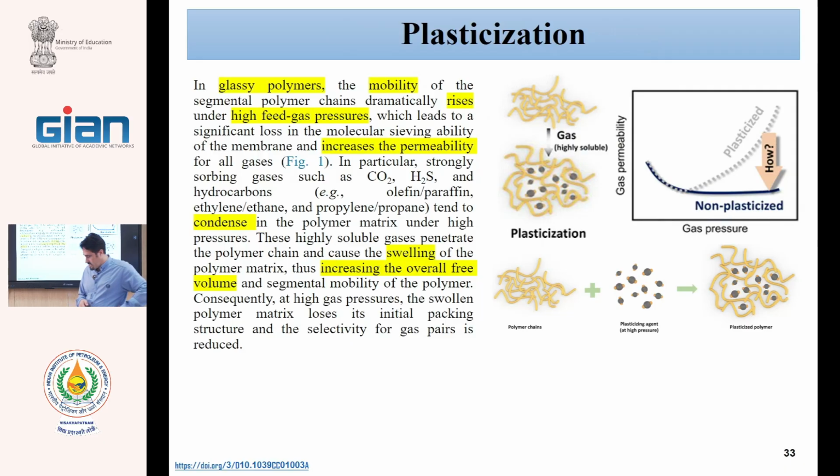In the liquid membrane filtration, MF, UF and others, we have fouling. That fouling causes a reduction of the performance. In gas separation, we also have fouling, but usually we do not say fouling. In this case, say aging or plasticization. Similar to fouling, the selectivity and permeance of the membrane change during time.